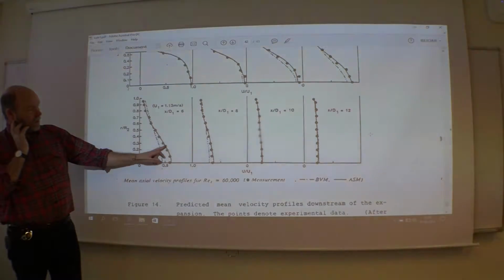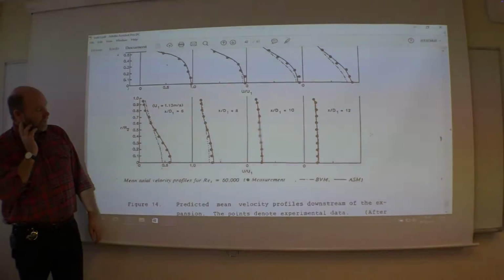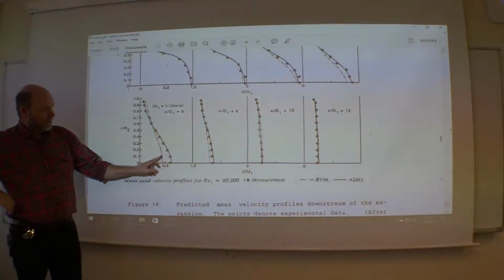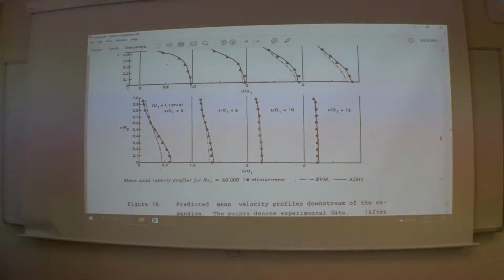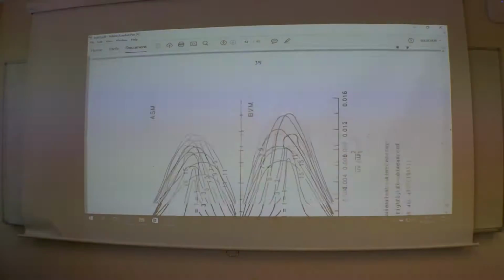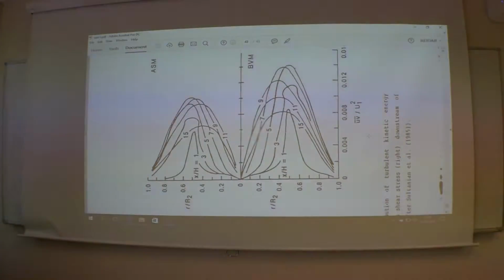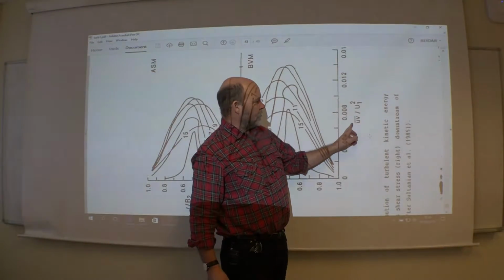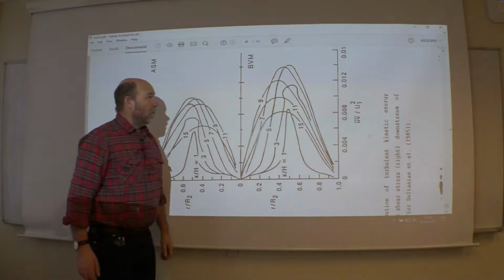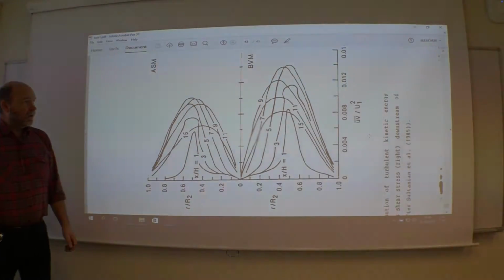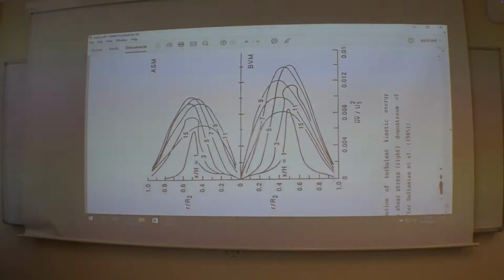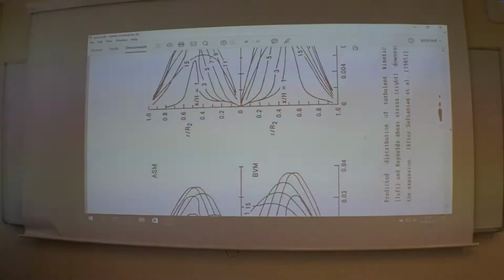And the ASM model can find the solution fairly decently. The K epsilon, no, it is not. It's not so nice. You see clearly here, looking at the different turbulent intensities, different Reynolds stresses. Well, of course, then the K epsilon will have an impossible job describing those accurately.